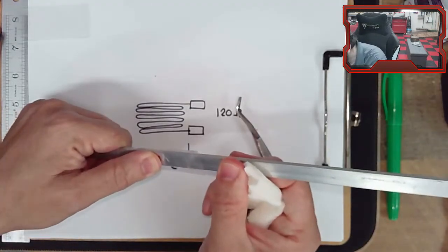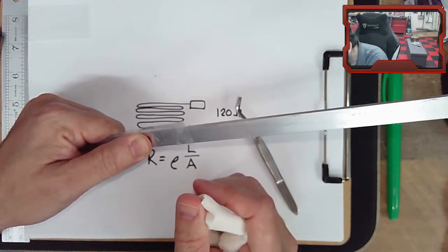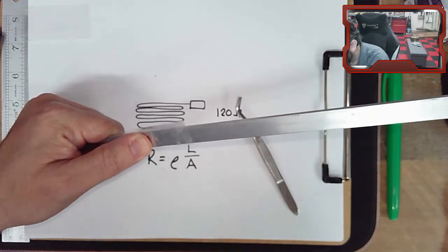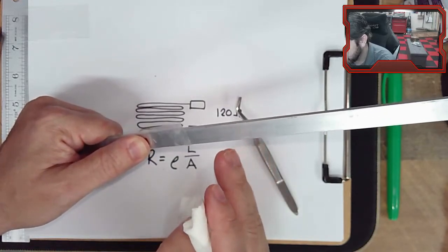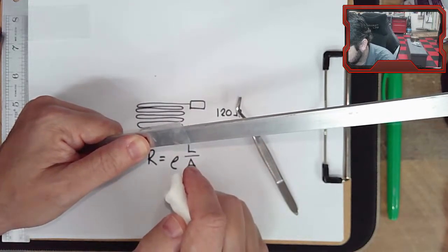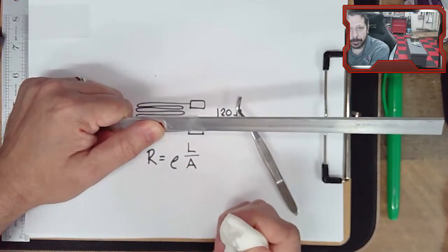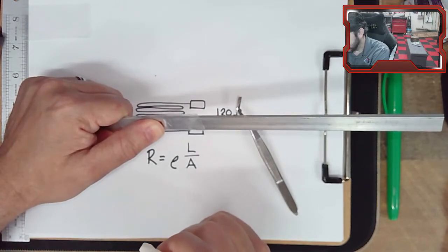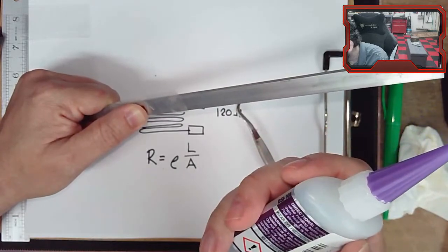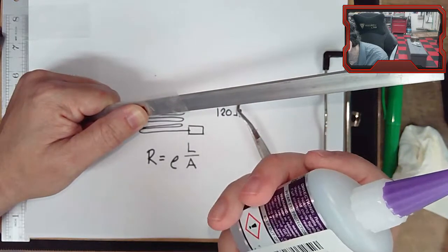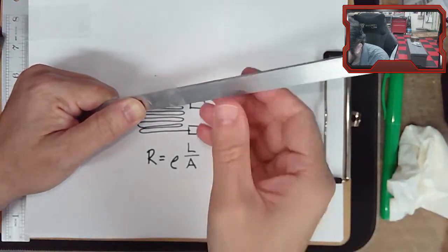So I'm just going to hold this for a minute to make sure it sets up, and then hopefully we'll be able to peel the tape off and leave the super glued strain gauge on, and that's mounting it. Now, if you're unsure if your glue is set, you can leave it to set for hours or whatever before we go on to the soldering phase. This one probably says something like 10 seconds is all you have to hold it. It's covered up with a label, so I can't read it, but typically it's like 10 seconds or something.